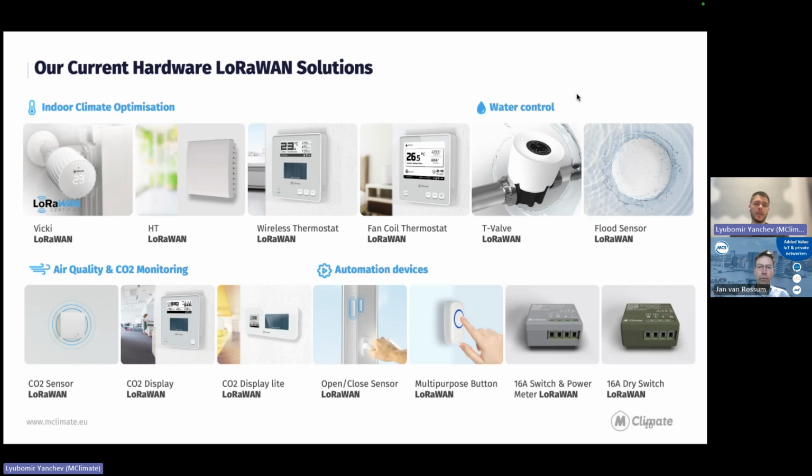It again works with LoRaWAN, has 2 typical AA batteries inside, but lasts for about 10 years, depending on spreading factor and how good the network is. On average, it should achieve 10 years. It gives you temperature, humidity, how open the valve in the radiator is, so how much hot water is flowing.